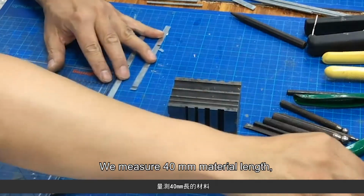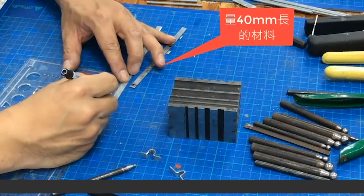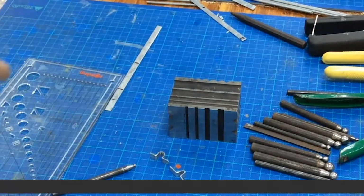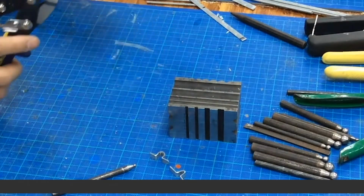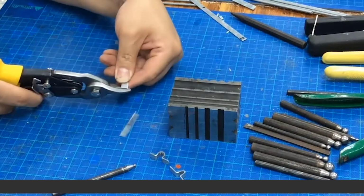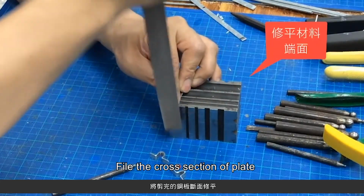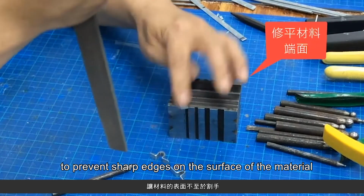We measure 40mm material length and cut it out. File the cross-section of the plate to prevent sharp edges on the surface of the material.